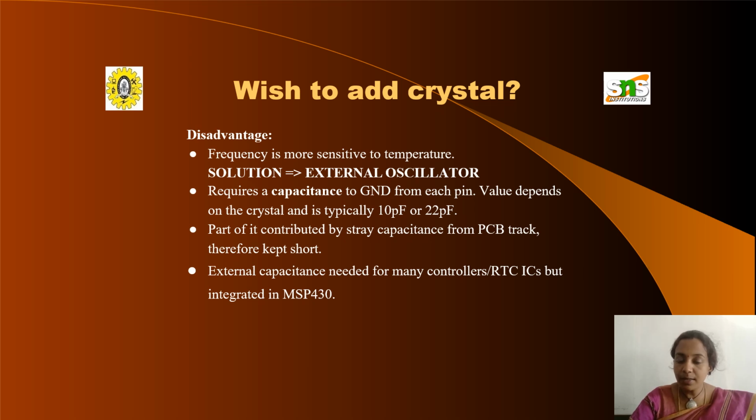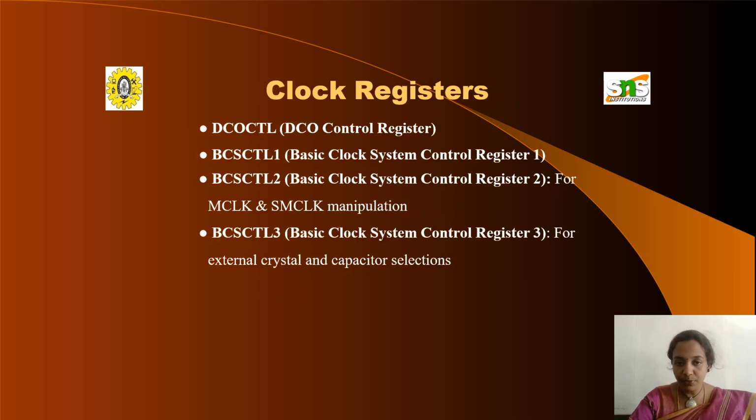The value depends on the crystal and is typically between 10 pF and 22 pF. Part of the capacitance value is contributed by stray capacitance from the PCB track, therefore it is kept short. External capacitance is needed for many controllers, RTC ICs, but it is integrated in the MSP430.